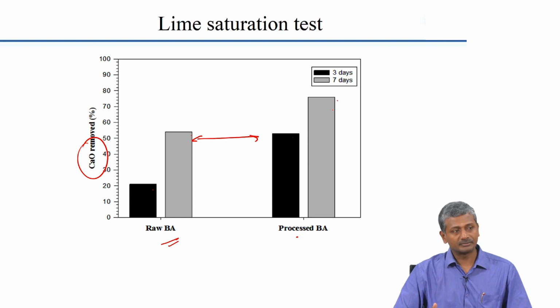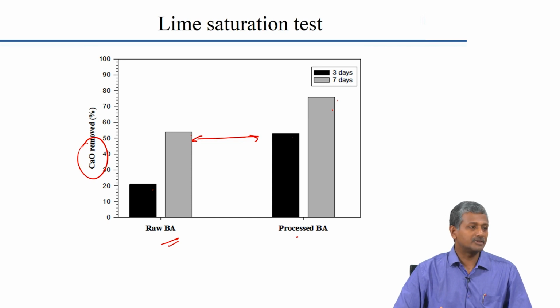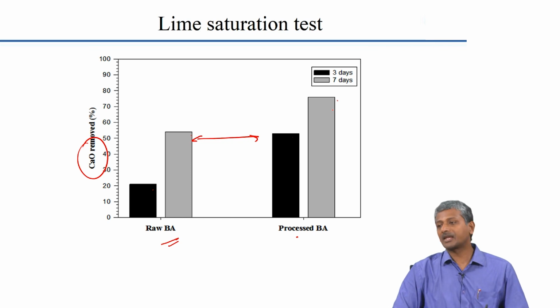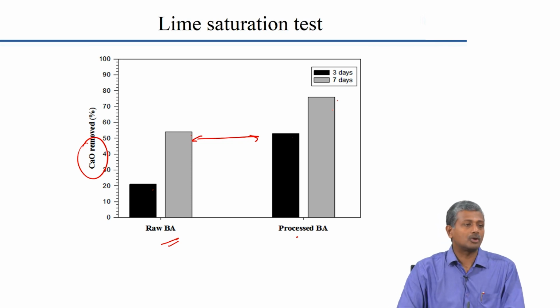Now, what does better mix proportioning imply? Finding the optimum levels of replacement of mineral admixtures in cement, right. We often do a trial and error method. We say okay, we will do 10%, 20%, 30%, 40%, and whichever gives us the maximization of properties, we will use. But this helps us reach there without too many trials, by simply understanding the fundamental characteristics of the material and seeing how much it will be able to contribute to the development of your structure in